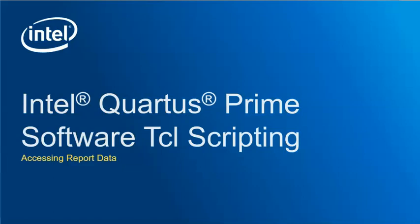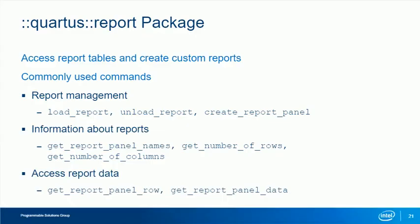After compiling the design, you'll want to get information from the compilation report. I'll talk about how to access report data next. The report package includes commands to access the Intel Quartus Prime report tables and data in those report tables and create custom reports. The report package is not loaded by default in most Intel Quartus Prime software executables, so don't forget to use the load_package report command.